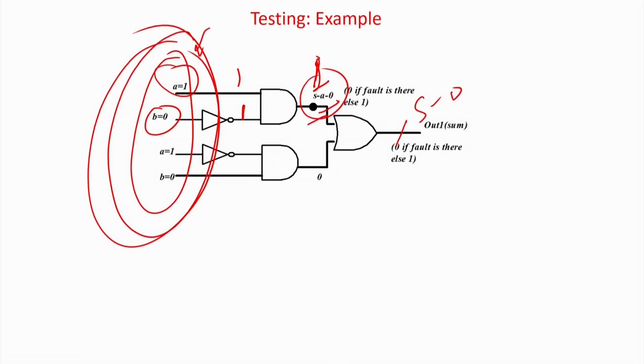That I will not do. If there is a test pattern which can test 100 faults, I will take that. So how can we generate good quality test patterns and also a very small set of test patterns, so that I can go for faster testing? But again, the test patterns have to be generated by automatic test pattern generation CAD tools, and they should also operate fast, so that I can get good quality test patterns at a faster rate.